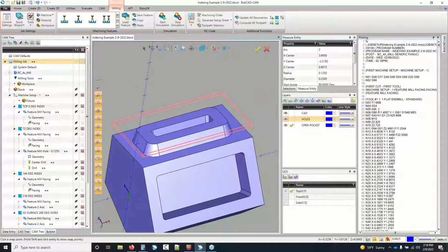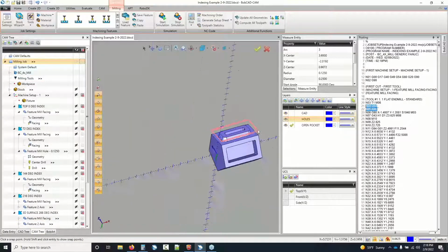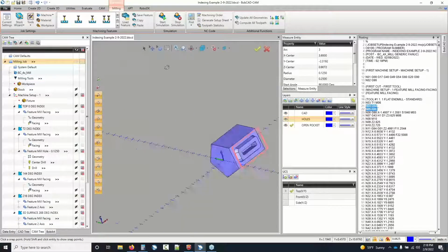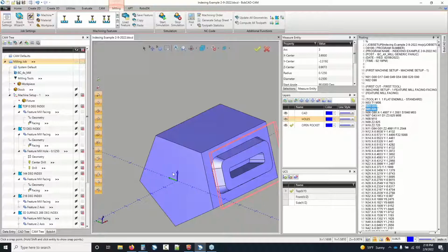And if I post my code, we'll see there's our A0, and that should be aligned with our Z-axis already, because I oriented this part so I had at least a flat surface here. And if we look at our origin, that lines us up there, and our index aligns perfectly with Z. Again, the reason I make sure to do that, even though I really don't need to, is because if I didn't have this thing perfectly square to that face, maybe there's a 1 or 2 degree angle, this is going to recognize it and make sure that everything else gets cut according to that.